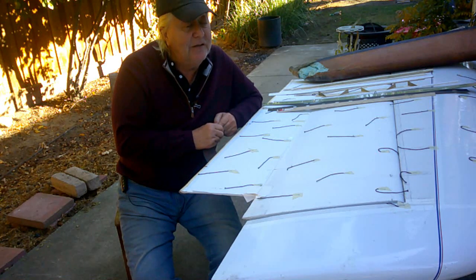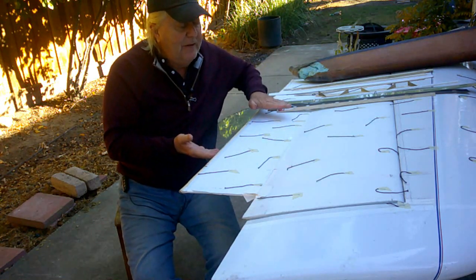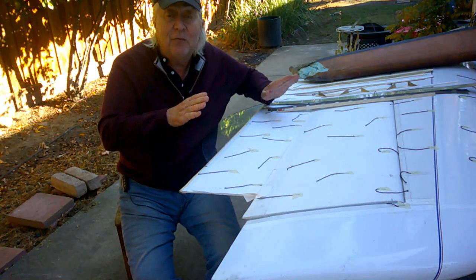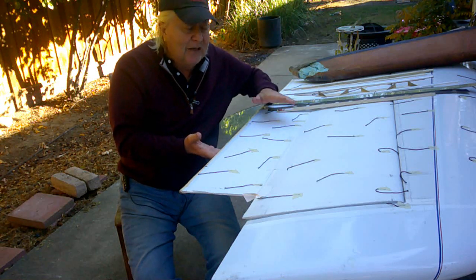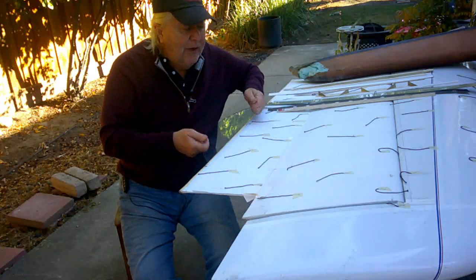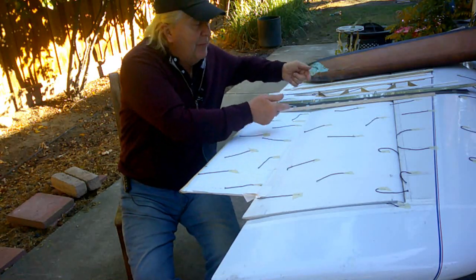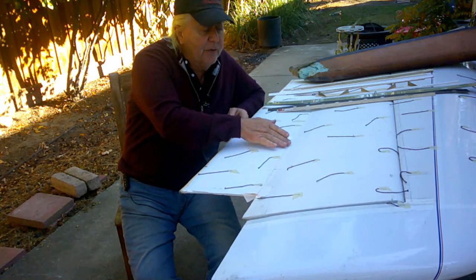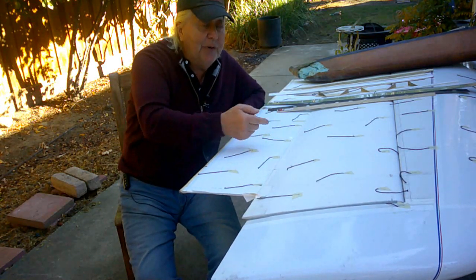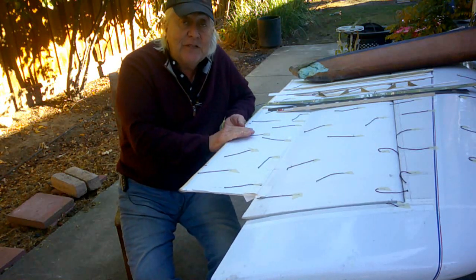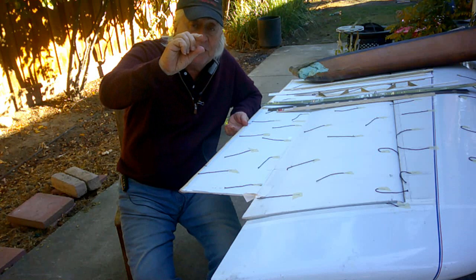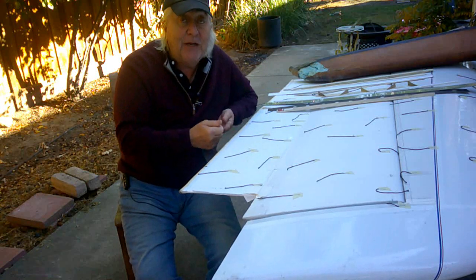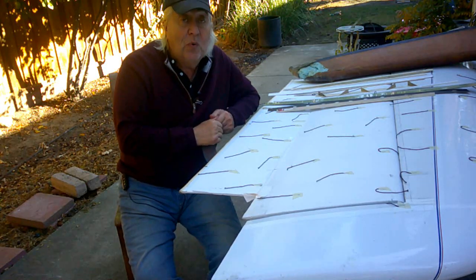Why were they stuck on the trailing edge? So I had my regular airfoil, and then when we would deploy the wing, you know, it's kind of like a Millennium. It had D-tubes and fabric and ribs that folded up, or like an Atos. And then you get the ribs deployed and attach the elevon, put in 3 pins, and you're good to go. And the receiver is the end of the ribs, right? The ribs had a little eye bolt in them, and you run a pin in there and attach your elevon. And the elevon was essentially a flat plate, so only 3/4 of an inch thick at the front, almost nothing at the back. So, for all intents compared to the airfoil, a flat plate tacked on to the trailing edge of the airfoil. Worked great.